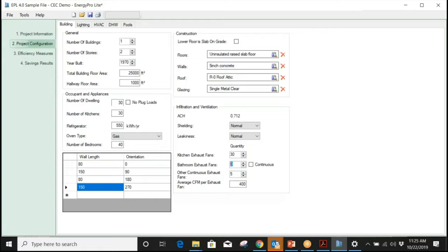So to rephrase what was just said here, if you have a recirculating fan in the kitchen or bathroom, you are not entering any information for that. It's only if it's exhausting. Maya, do you want to add to that? No, I think that was all correct. And then I would just clarify, when it really comes down to it, what are we looking at? We're looking at infiltration and ventilation. So just kind of keep that in the back of your head as you're working through these questions. Yeah, these recirc fans are just recirculating air within the building. They're not ventilating in any way.